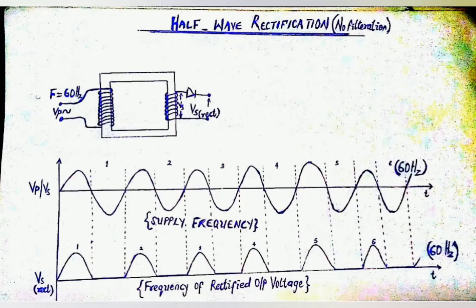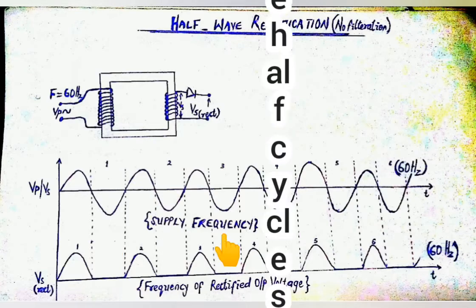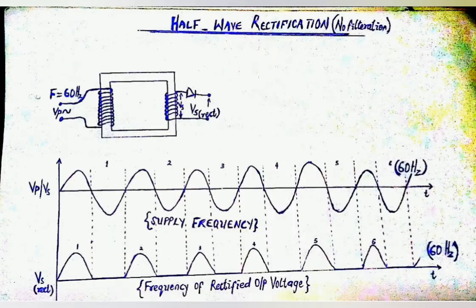This means that current flows through the output part of the rectifier only during the positive half-cycles of the input voltage. During the negative half-cycles, there is no voltage at the rectifier output till another positive half-cycle of the input voltage waveform reaches again.